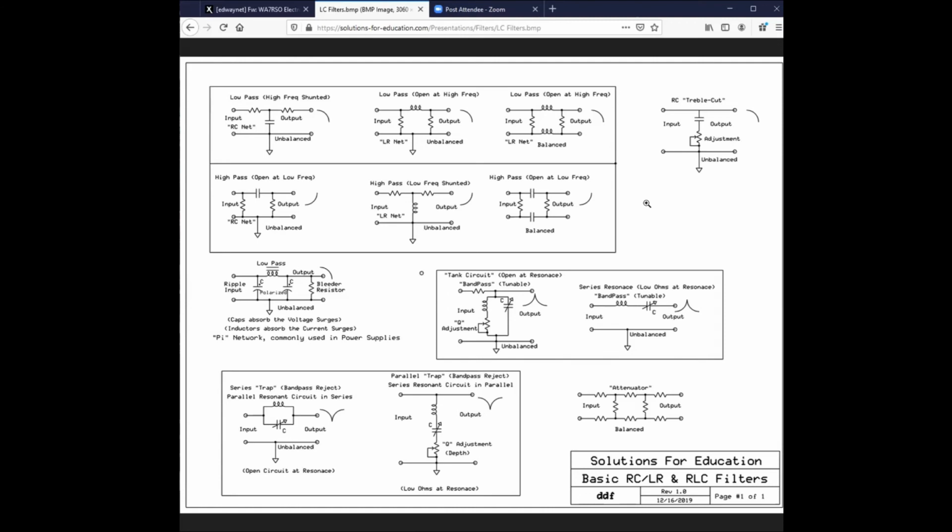And then I used high-speed interrupts with high-speed buffering systems, because we would read the data off of the hard drive into a buffer, which went through a D to A converter down to the shaker tables. Then we had the data coming back from the shaker tables into another high-speed interrupt buffer system, which I would then write as data on the hard drive. All this had to happen without any mishaps at all.